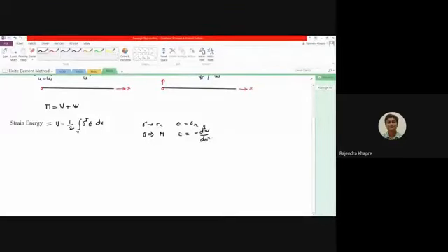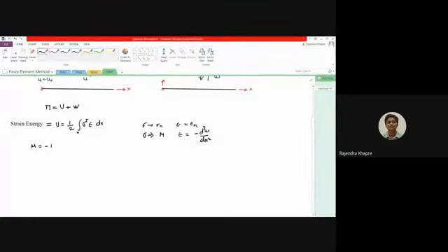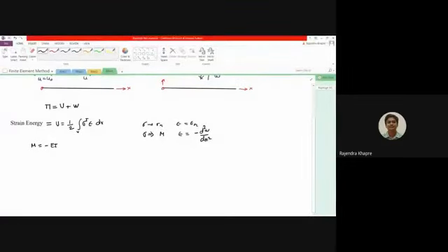This is the expression which we have to write down over here. Now what is m? M is nothing but the expression for the moment. If you remember your second year strength of materials, this m can be calculated as minus EI d square w by dx square. I hope you remember this particular expression.